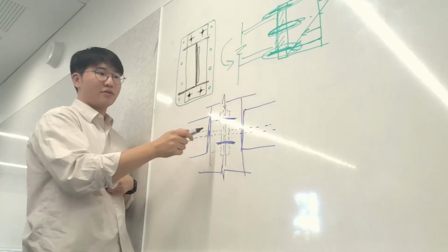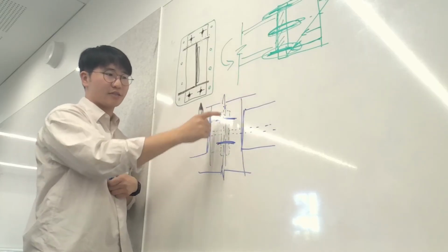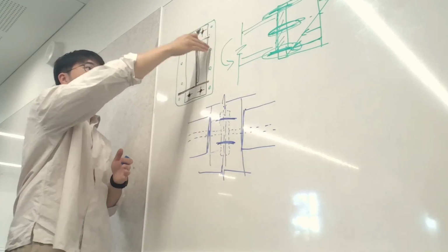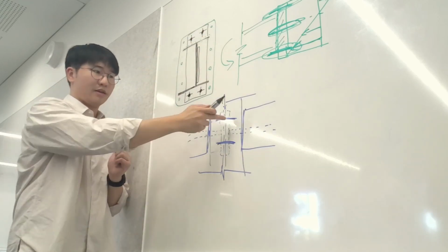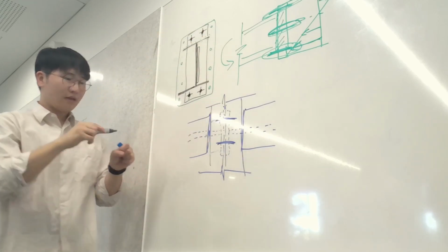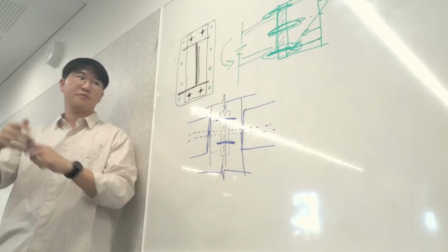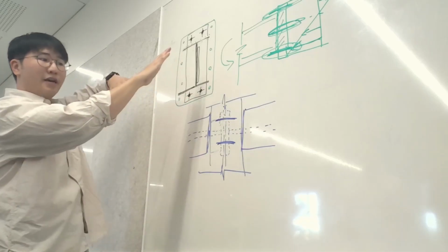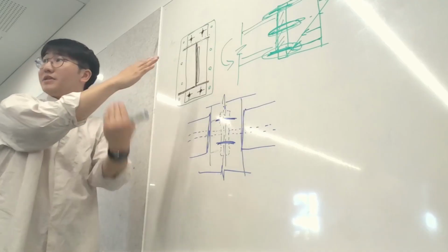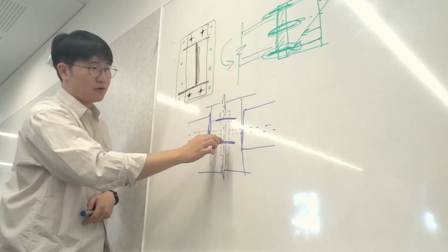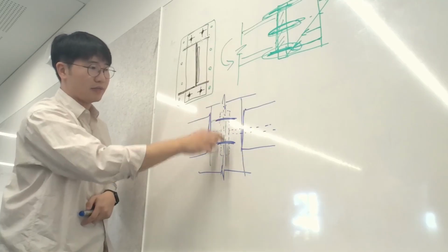Right, so that's a bolt. Sorry, I should draw the bolt dashed because it's underneath technically. But there might be like 3 rows of bolts underneath there. Okay. But this still allows for a bit of rotation. So you might imagine that one's coming, and then if this bends, you've just got 2 pins basically, because it's a little bit more pin than if this was a cleat, but it's got an end plate,